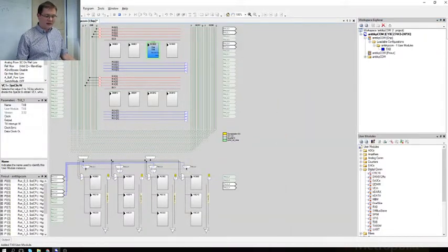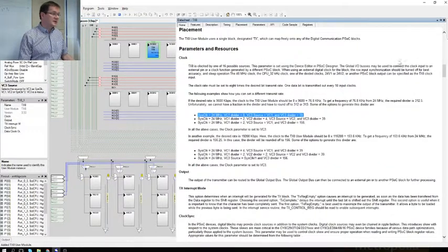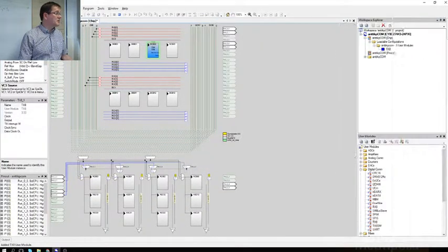So the clock divider for SysClk1 is 8, and then, let's see how does it go. VC3 source is VC1, and the divider is 39. Okay, I think I remember those. So the VC3 clock source is VC1, and the divider here is 39. This gives a close enough clock signal for that module.